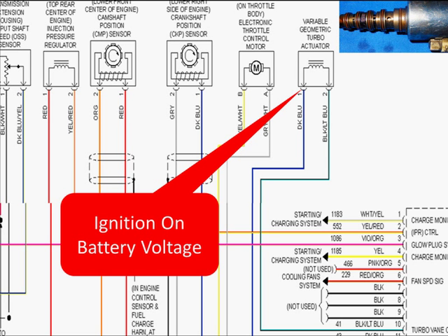We have battery voltage coming to pin 2, and we're going to supply ground to energize the actuator. So with the key on, engine off, we should see battery voltage with 0% duty cycle. As we start the vehicle up and get it running, we will see this voltage start varying as the duty cycle varies. If you have any problems with this, you need to get good B+, you need to get ground working. If you don't get these, you need to go back and diagnose the wiring and the electrical system to find out why.